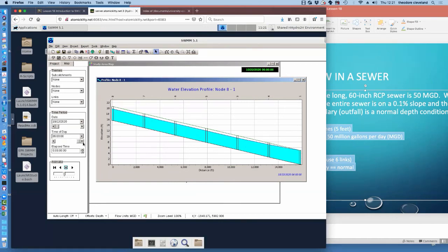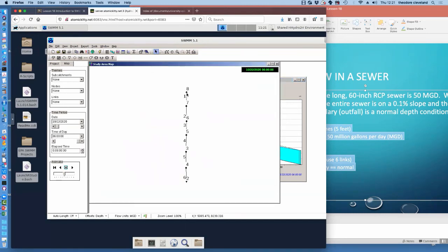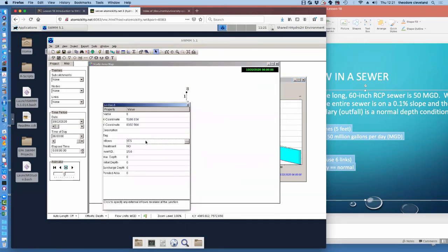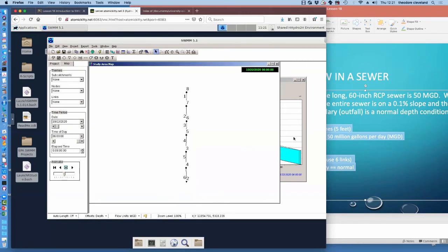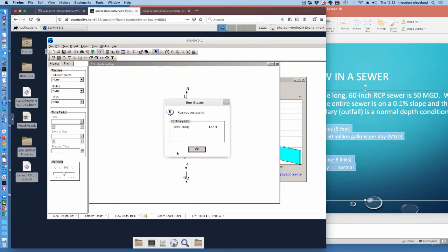So that's just catching the top of the pipe at the downstream end. It may not even be able to accommodate 46 million gallons per day, but somewhere between 45 and 46 would be a good design flow for this particular system, because all the water is contained in the pipe. And we'll look at ways to accommodate water being stored on the surface in a different meeting, because we're almost done with today.